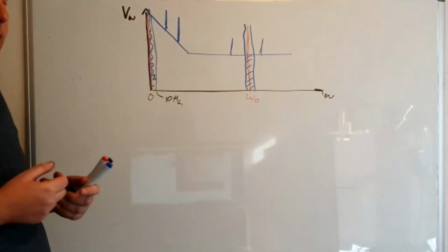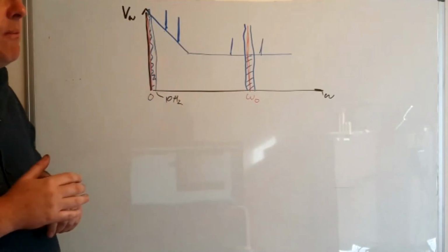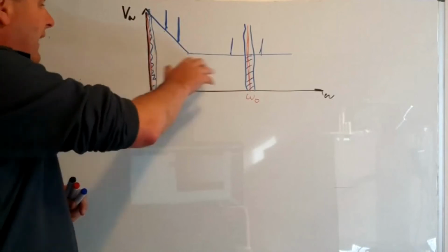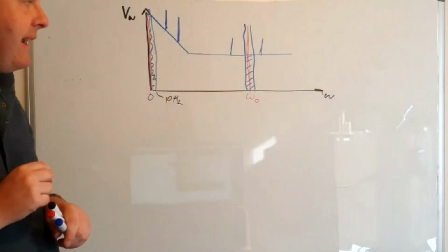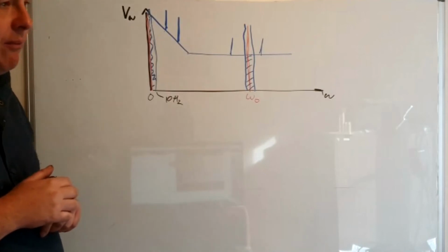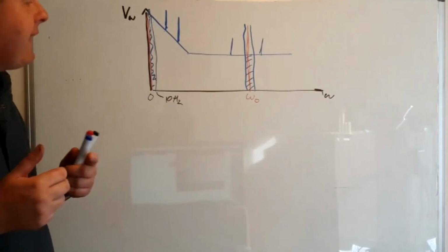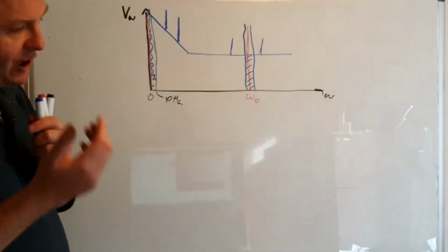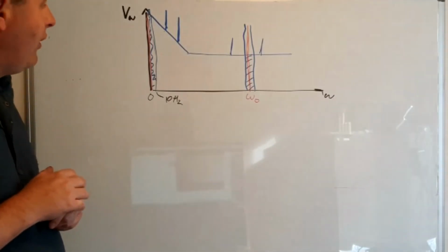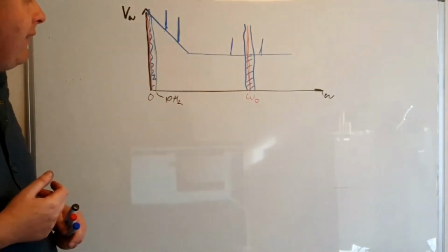It's not even just where you've got a lock-in amplifier, obviously there, but in many cases you'll find that there is in fact a phase sensitive detection process hidden away in the background in many, many different types of instruments. And so understanding the effect of changing the frequency, of changing the amount of time you average the signals for, gets you to understand why certain combinations of things are going to work well.